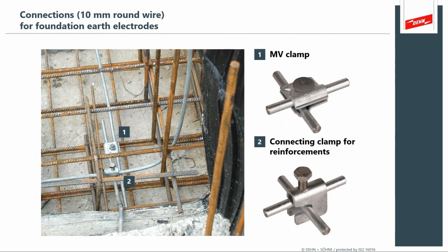I've got a couple of nice illustrations and photographs showing the actual rebar steel connected to the down conductor systems. And what's nice here is that in this photograph, you can see this is really common. If you've done a lot of concrete work, you'll see these straps that hold the rebar in position, but that is not an electrical connection.